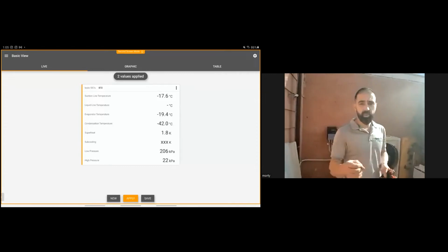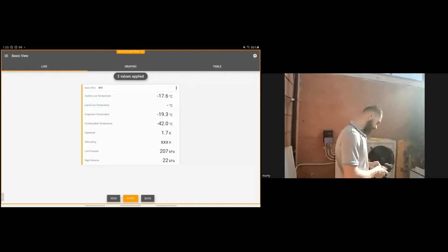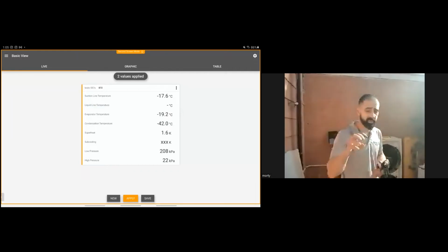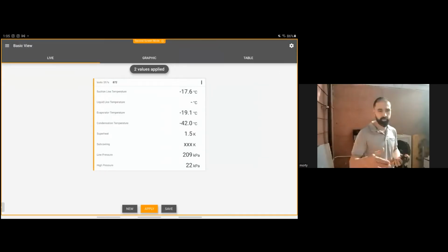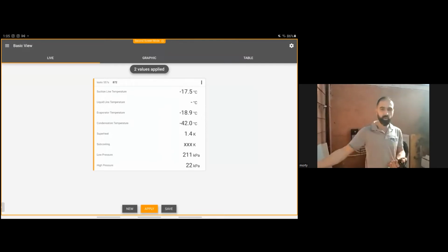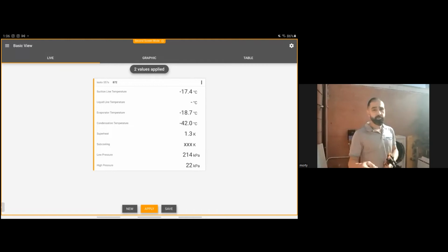Once it gets to the temperature where, if your set point is at 0 and your termination at 0, and then back on at 2 or 3 degrees, depending on your differential set point, I would adjust around the 5 degree mark.